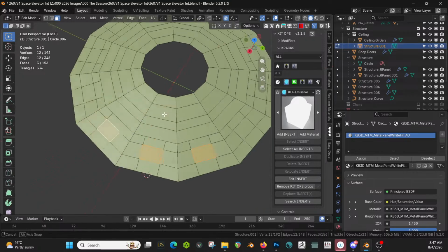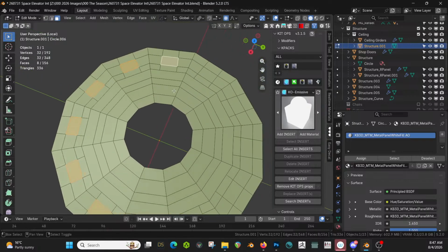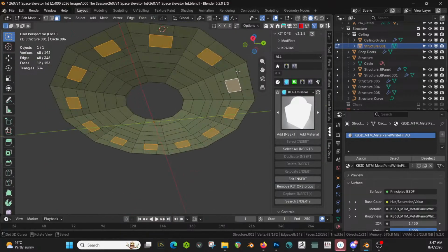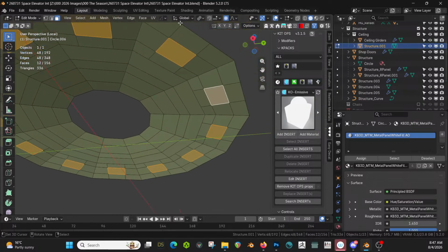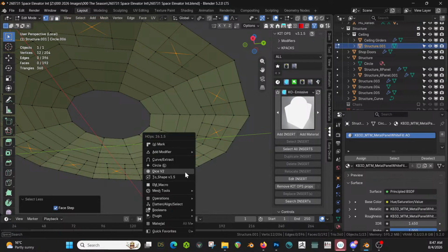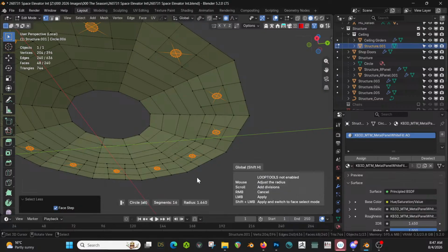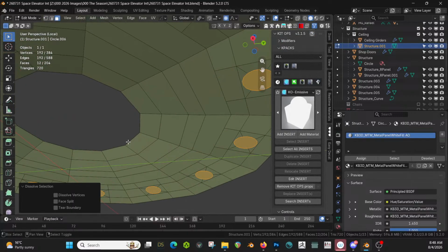So we can select these. We'll do these a little bit at a time. We don't necessarily have to have the same size lighting throughout the whole thing. So let's just do those. Now, do we want circular? Do we want rounded edges? Or do we want square lights? I think we want circular. Face, poke faces, 1, minus Q. Circle. Up to there. 3. Good.